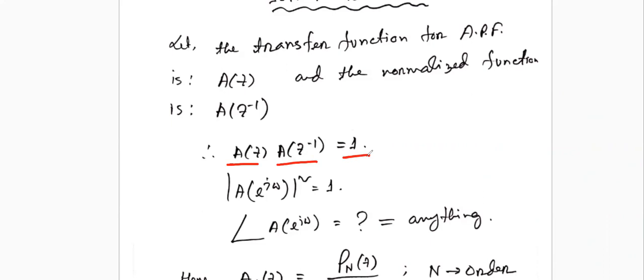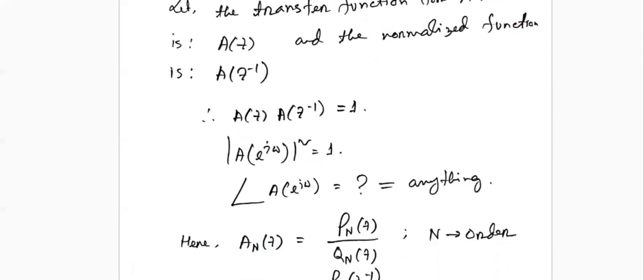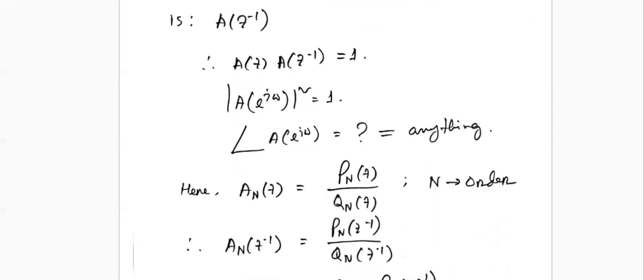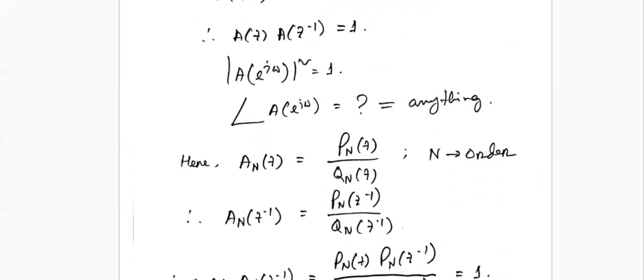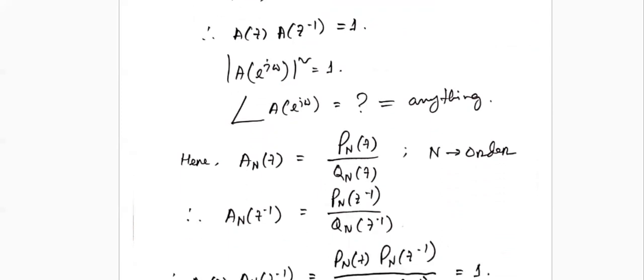Sometimes we need this inverse filter part as well. We can design it very easily. If you have this, you can design it from your Z domain representation. From there, we can also find the magnitude response, the power spectrum of the all pass filter, because A is representing the all pass filter. The thing is very simple here. That means everywhere the magnitude is equal to 1.